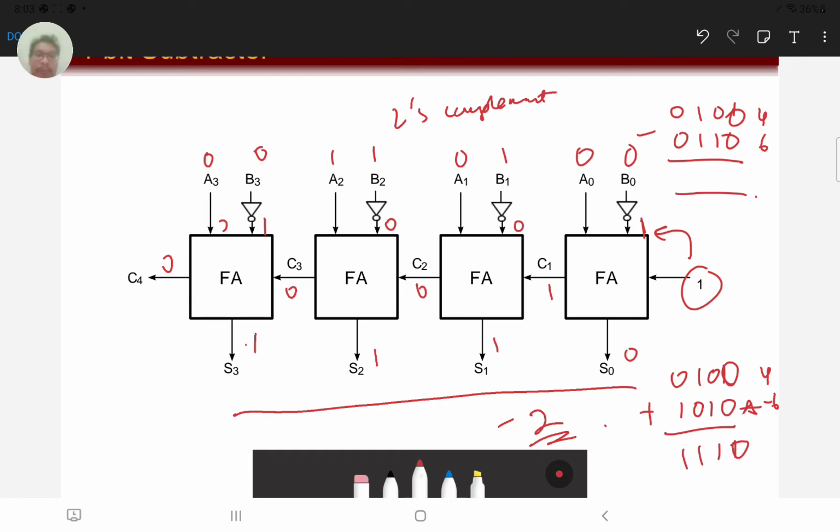Okay, so basically 2 steps. Just to repeat here, basically 2 steps to convert an adder to a subtractor. Step 1 is to have a 1 in the carry. Because we need to do a complement and add 1. The second step is to add these inverters to invert the b values. So we basically invert the b values plus 1 on the carry, and then we do a plus the 2's complement of b to obtain the subtraction value.